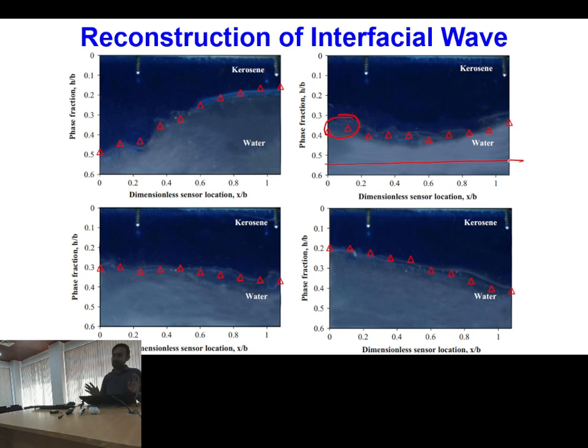But in the previous configurations where you have simply a straight oscillating interface, the nature of the interface is almost planar. And when the whole platform is moving at a particular speed, your interface profile is also steady. But when you have a random wavy structure, with a number of waves passing, reflecting from the tank wall and coming back, you will find that the shape of the interface will not be purely two-dimensional or purely planar.